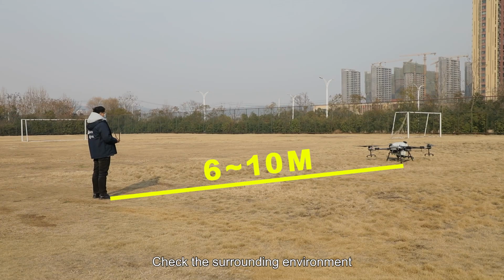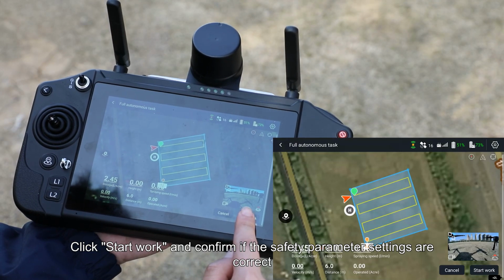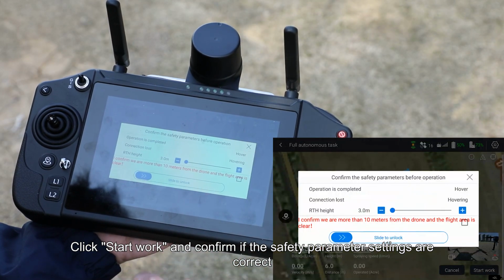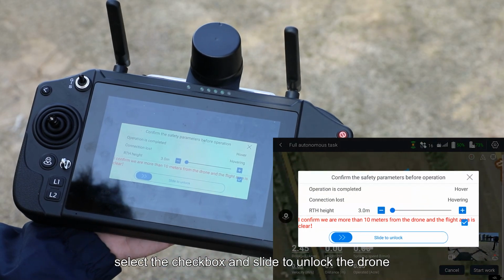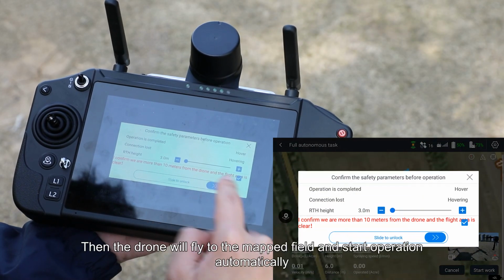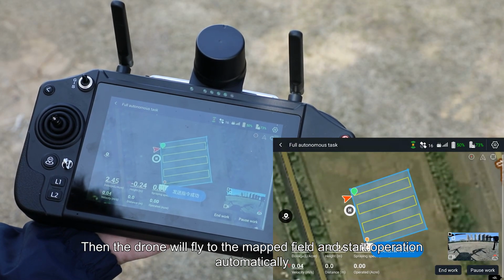5. Start the operation. Check the surrounding environment. The pilot should keep a safe distance of 6 to 10 meters from the drone. Click Start Work and confirm if the safety parameter settings are correct. After confirmation, select the checkbox and slide to unlock the drone. Then the drone will fly to the mapped field and start operation automatically.